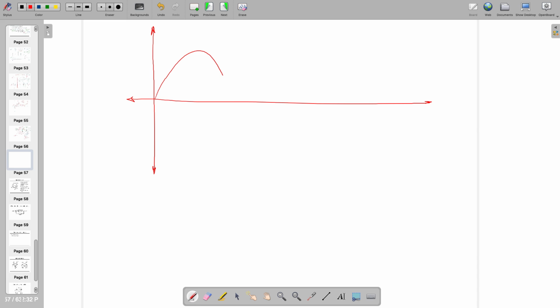If you want to take output like this output I am observing in DSO, and I don't have a spectrum analyzer, let's assume that. Actually, that's the fact at IIT Mandi also. I don't have a spectrum analyzer. So I'm going to DSO, I'm plotting this, I'm taking this to MATLAB, and then I'm converting it to a frequency signal.